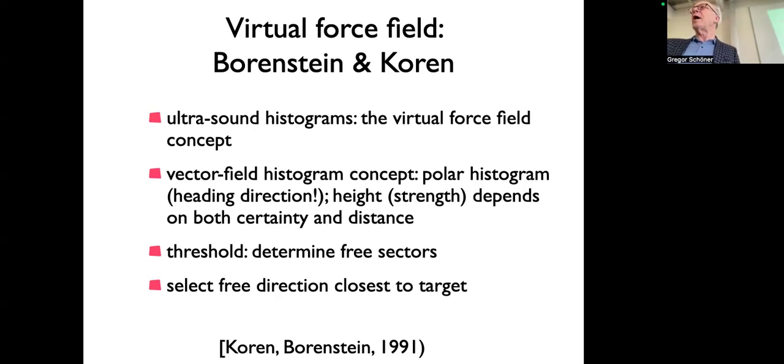That's true for radar as well. Some of you might know that. For instance, ships have this radar reflector. You have a little cube with metallic, reflective surfaces at right angles to each other, and this makes it so that from any direction you get an echo. This is so that on the radar you see your ship. You don't miss the ship because you really want to avoid collision with ships or track them and so on.